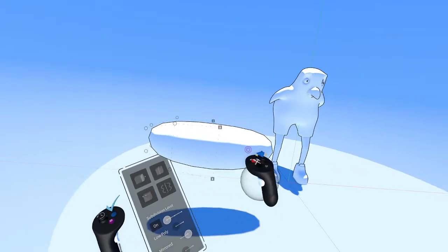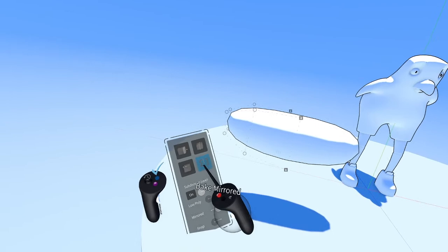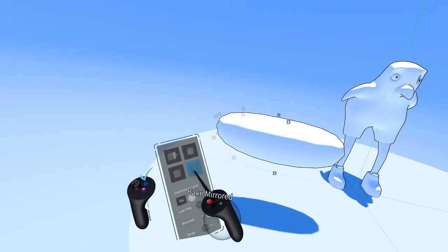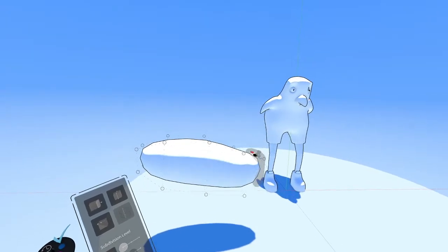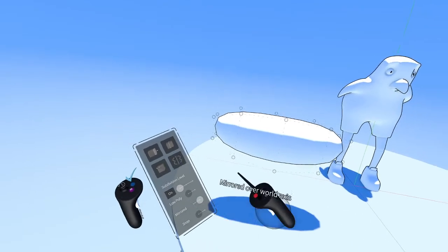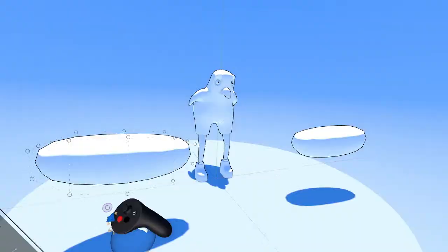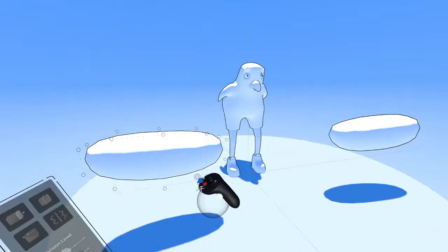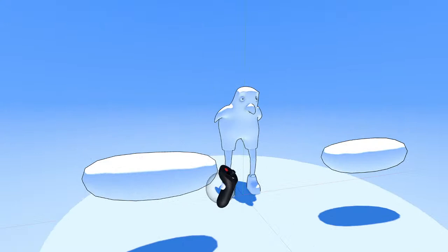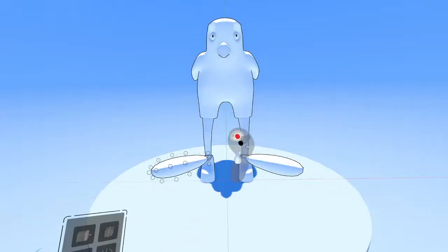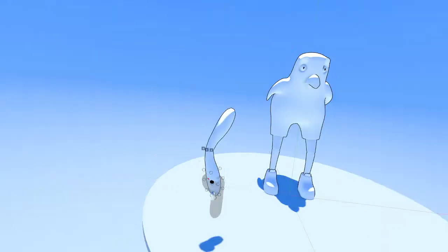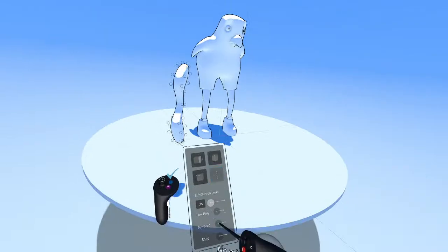And then if you wanted to break that mirror, you could come here into the edit panel, press bake mirror, and so now we have a solid object. The mirror has been broken, but we can turn on mirror again and have that full object mirrored on the other side again. And then just keep doing that. We can connect it, shift it off the mirror plane, do the same thing. Bake it, mirror it again.